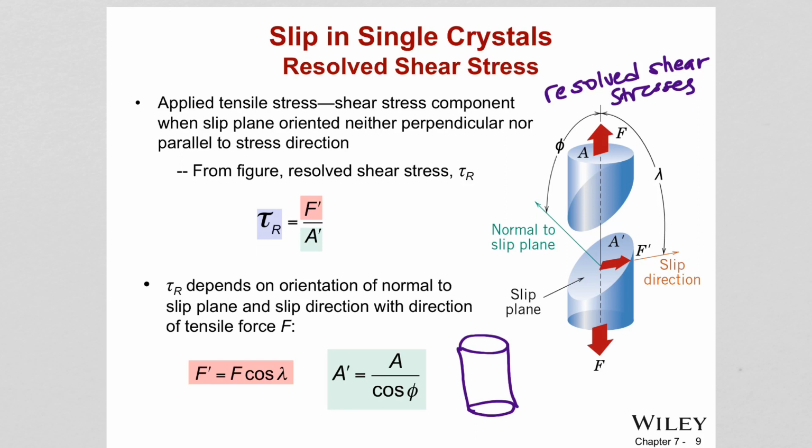In polycrystals all grains will have different directions of atoms, so all will have slip systems in different directions from each other, randomly distributed. So let us just consider a simple single crystal, so we understand how we have force components and how shear is generated and exposed to the layers of atoms, and therefore how deformation happens. So let's look at the resolved shear stresses.